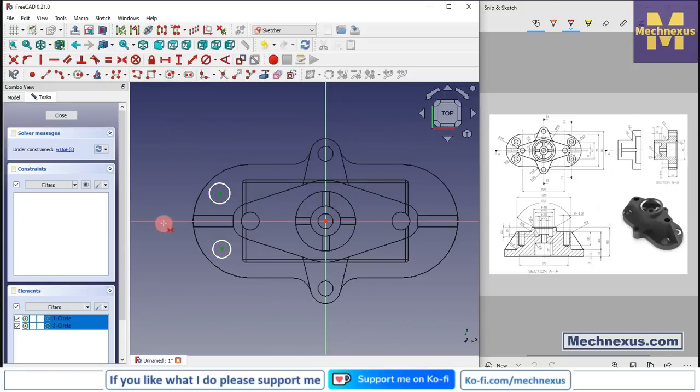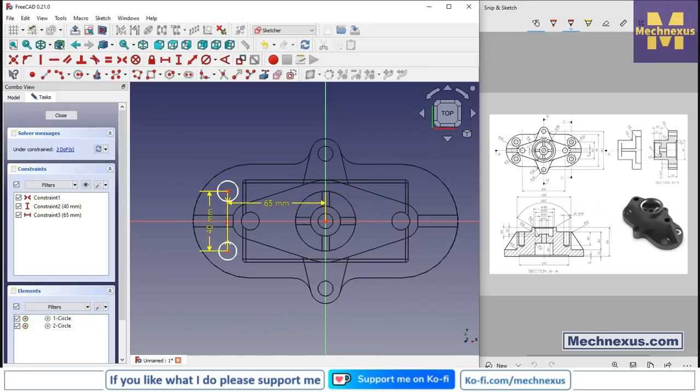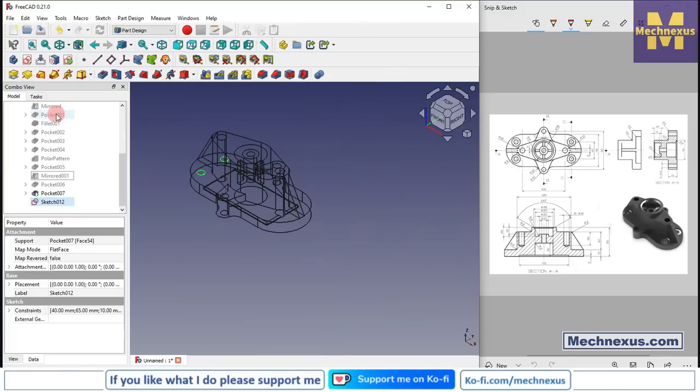Select this point and this axis, and select a vertical dimension and provide it 40, and select a horizontal dimension, select this and add 65, and this is of a diameter 10, so select diameter and provide the 10 mm, and select this and make it equal. Click on close, press V7 for shaded view, and here